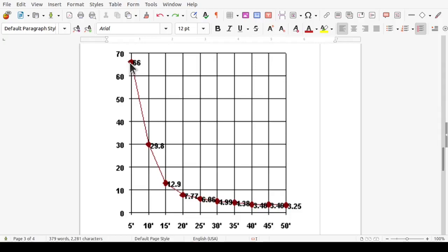at that point. And again, the other point is the remote, leadless resistive side of Earth that's infinite. If we were to double that depth, we pretty much halve the resistance, 29.8.